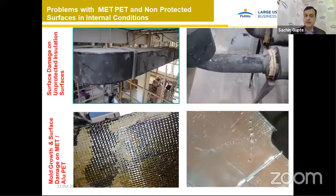Now we come down to the internal applications. This is what you see whenever you enter an office, whether an ongoing building or one that's been constructed. It could be an IT building, hospitals, any kind of building. The black material you see is called nitrile rubber. Typically, you will find these kinds of cracks. These cracks are caused by other agencies that are working. Their tools and tackles start falling down, or they put their screwdriver on the soft surface and a crack is developed. The moment a crack is developed, it loses its insulation property and becomes a potential source of surface condensation.